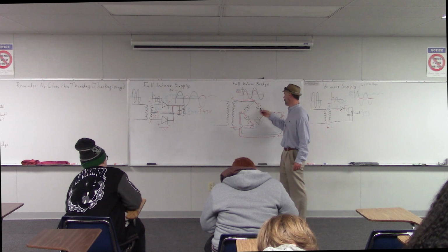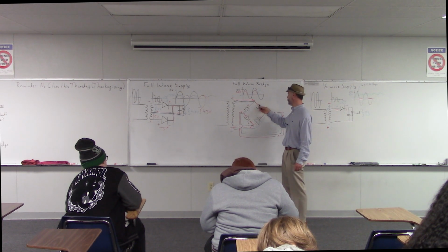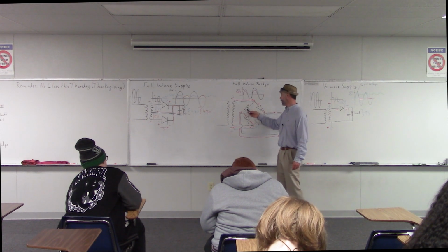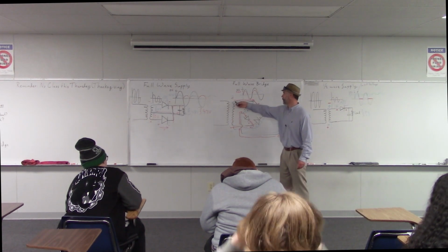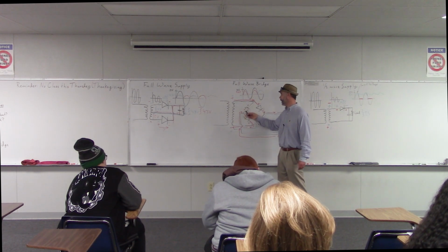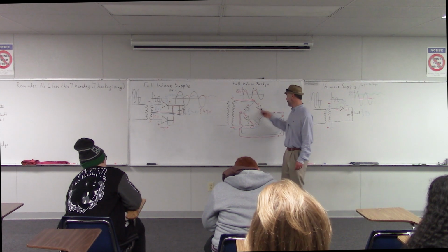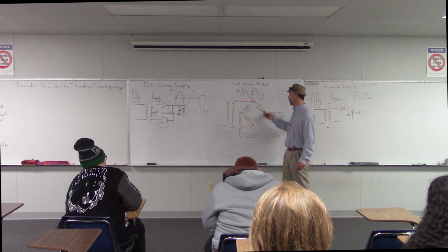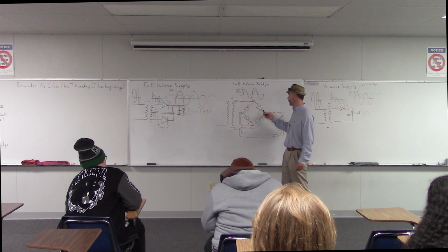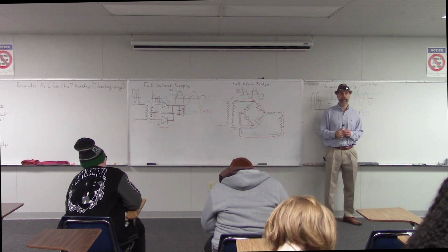In this case, the anode is closer to the positive voltage, and so it gets the positive charge. Over on this one, the cathode is closer to the positive voltage, so it gets the positive charge there, and the negative is on the anode. So that means that this diode is forward biased, and this one is reverse biased. That clears up a lot. Okay. Sure.